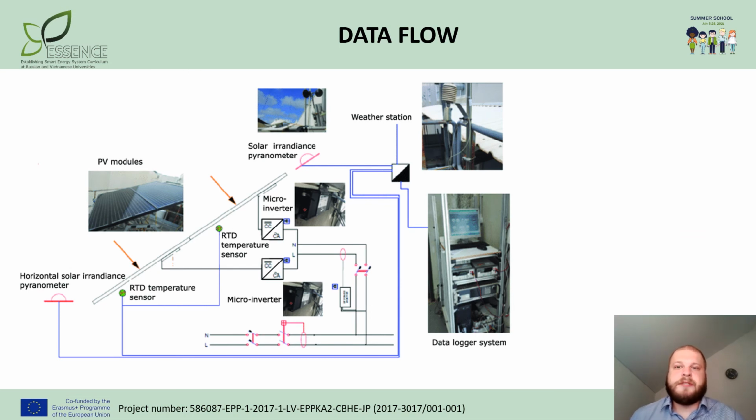Well, now let's talk about data flow within the framework of the photovoltaic power plant. Let's consider the different data sources associated with the PV panel. For a PV panel, we have temperature sensors, which provide data on the temperature of the surface of the solar panel, which has a great impact on photovoltaic panel production efficiency. Within the framework of the PV power plant, we have a horizontally installed solar irradiance pyranometer and a solar irradiance pyranometer which is tilted in the same plane